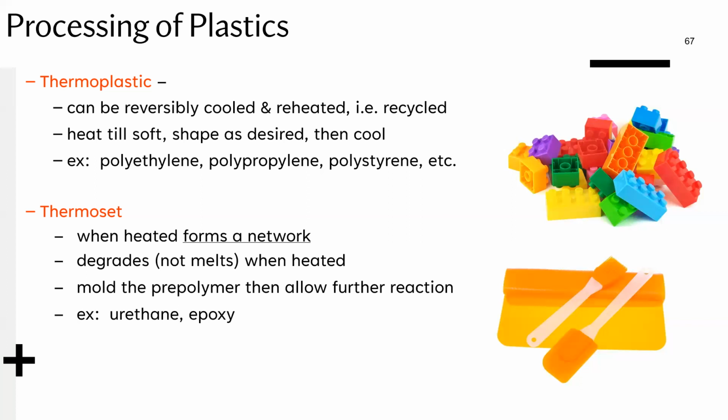So really the materials that are useful for processing, especially at reasonably low temperatures, are going to be the thermoplastics. Okay, so what is a good temperature? You've already noticed that what we're going to use is temperature. So we're going to be using temperature to heat these stock materials up to a temperature where they can be deformed, and then we're going to use a manufacturing process to shape them.